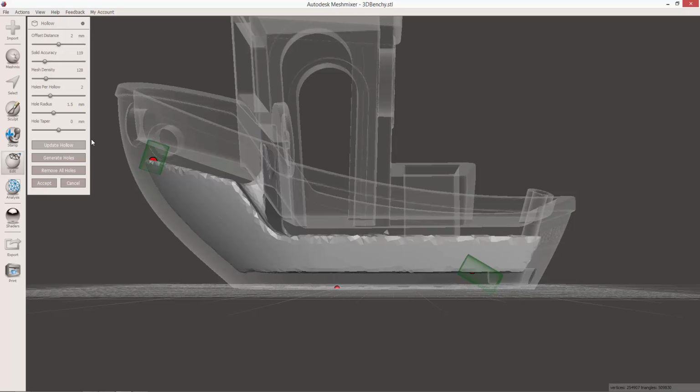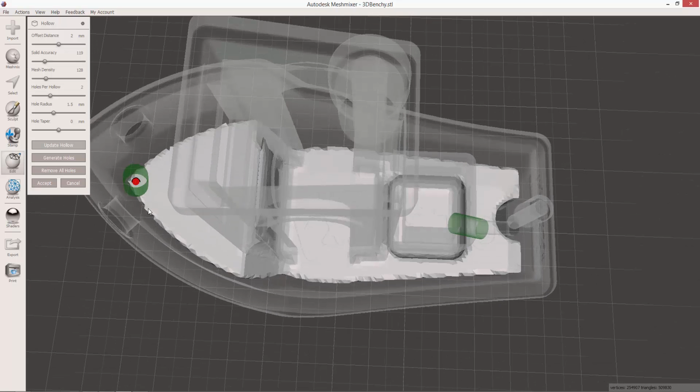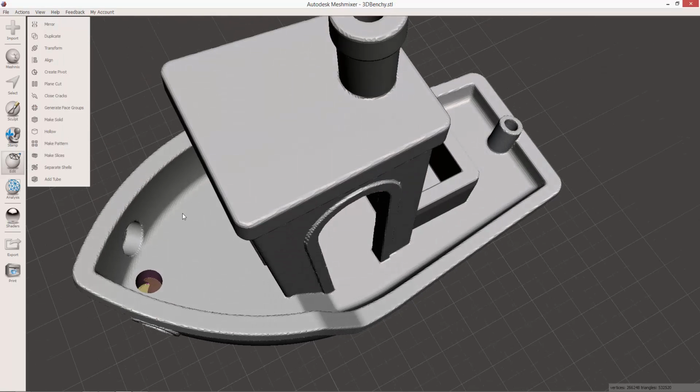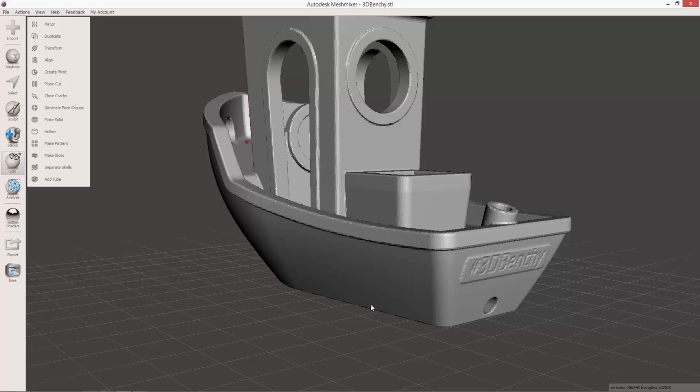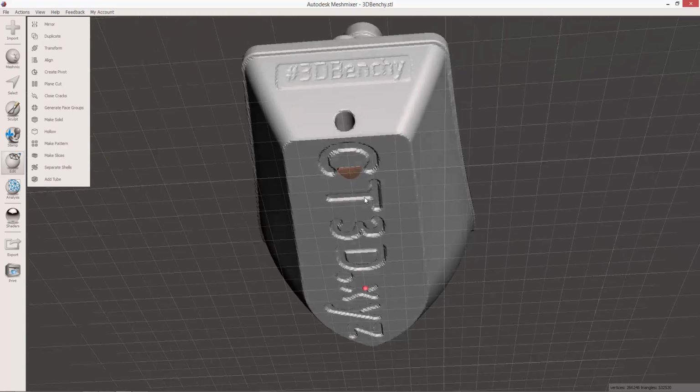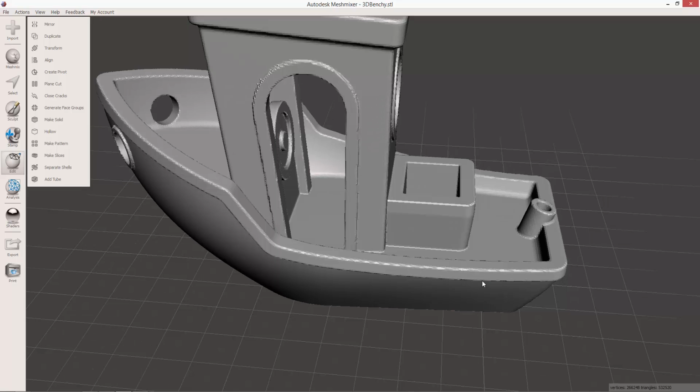I'm going to probably have to reduce the size of these holes if I really wanted it, but it turns out that there's a bunch of steps more I would have to do if I wanted these holes to work, because the mesh density of some of these surfaces is very low, and so there'll be weird side effects from adding these holes, because the mesh density won't be high enough on these smooth regions to accommodate the holes well. And so you'll see that there's some wrinkling and then some weird things have happened here. In any case, I'm not really going to